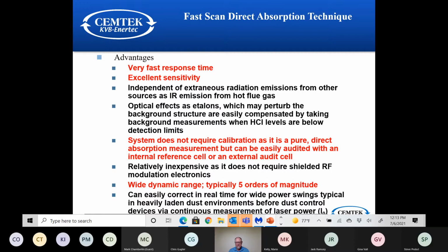If we're not reading the gas, then there's something wrong with the instrument, which even that rarely happens. So we have gas that we can flow through them to test them, and we can pass daily calibrations in a couple of different ways, which I'll get to. But it really doesn't need to be calibrated. They just don't drift.